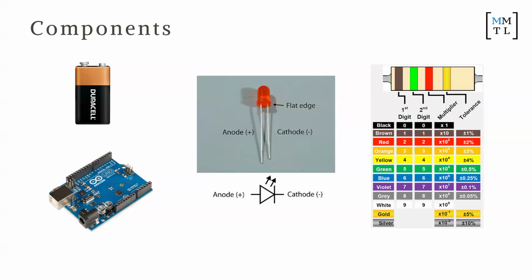All right, the final component is a resistor. Like I said before, you must have a resistor between 5 volts and ground. How resistors work is that there is a coloring scheme, where it tells you what the first digit is, what the second digit is, and then what the multiplier is. There's sometimes an optional fourth band, which tells you the tolerance of the resistor.